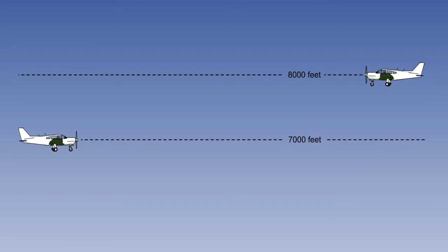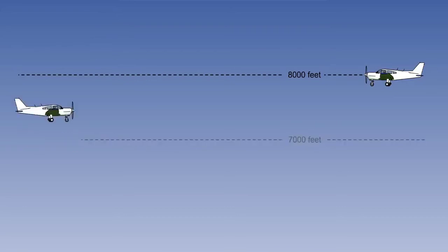However, suppose that one aircraft has corrected for barometric and temperature error at a departure airport, where the sea level pressure and the temperature are lower than when they meet, and has not altered it since. His true altitude will be here.